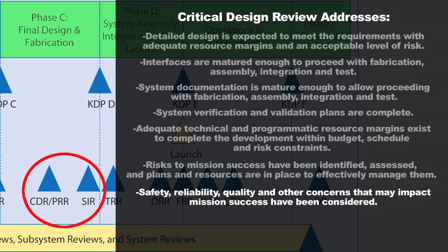And this is where you may have already, prior to the critical design review, started to procure some long lead parts. And there's always a process that says, gee, if I haven't finished my design, should I really allow anyone to go off and buy any long lead parts? Because maybe those parts will be the wrong parts once I've completed my critical design review, because the design may have changed a bit. Well, in some cases, it'll take years to develop flight hardware. And so sometimes you have to build some of the components before you actually get through this review.